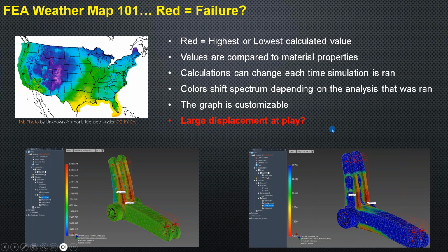And then large displacements, are they coming into play? That's another big question you have to ask yourself. When you get these results, is there any large displacement amount? And I cannot give you a magic number that says above this amount is a large displacement, below this amount is not. It doesn't work that way either. It's relative back to the overall size of your component. That's something we're going to look at here briefly.